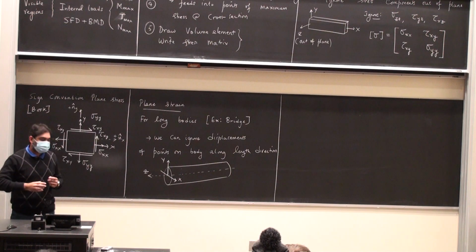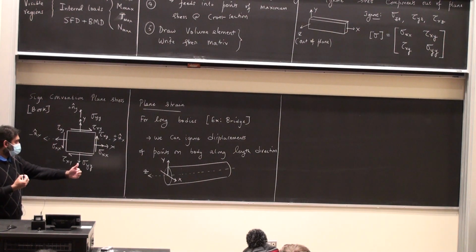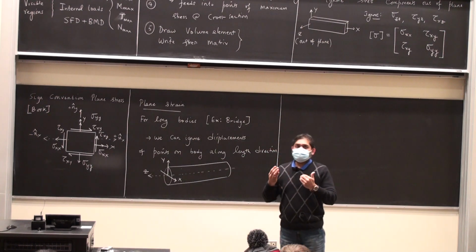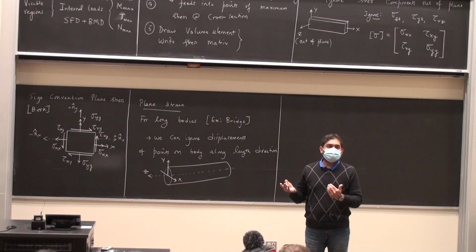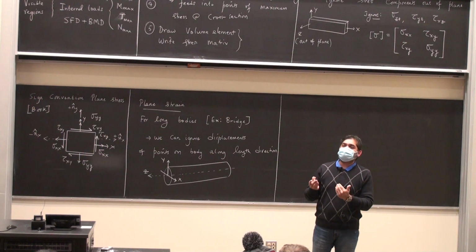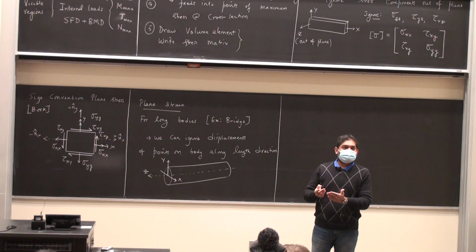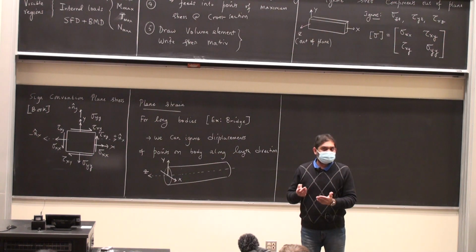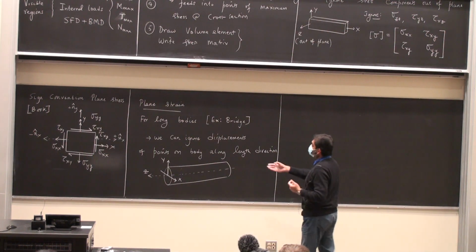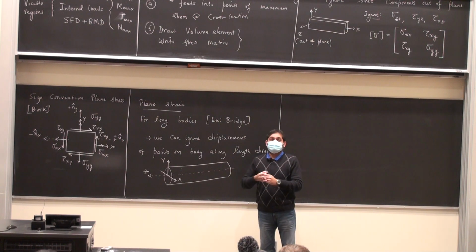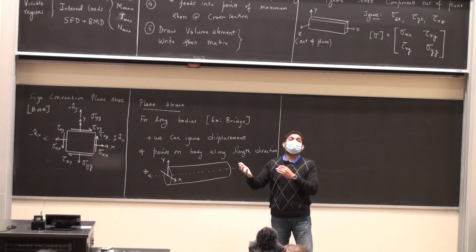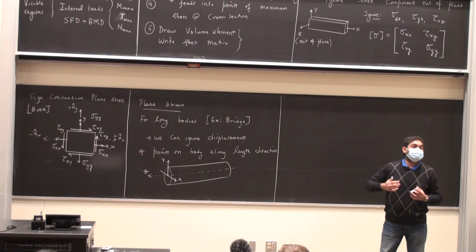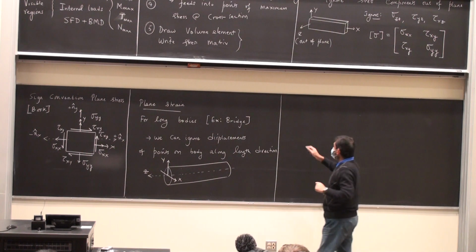This is the z-axis. What is the longest direction here? Typically the z direction, right? If the displacements are negligible, what is strain? Strain is nothing but displacement divided by the initial length of the body, in some sense. So which essentially means that if the displacements along the z direction are negligible, then all the strain components along the z direction are negligible, and like we had 6 stress components, we usually have 6 strain components as well. So typically the strain